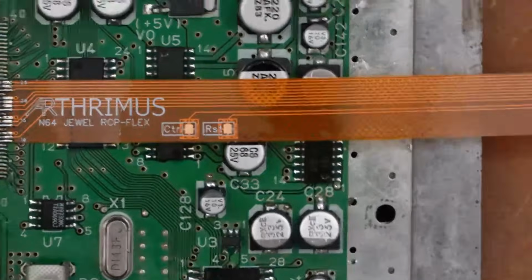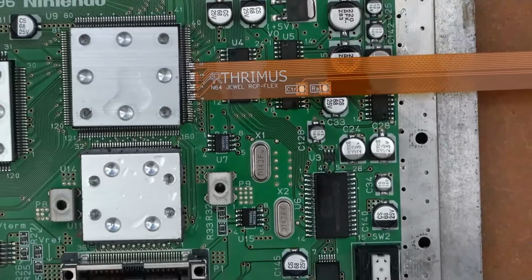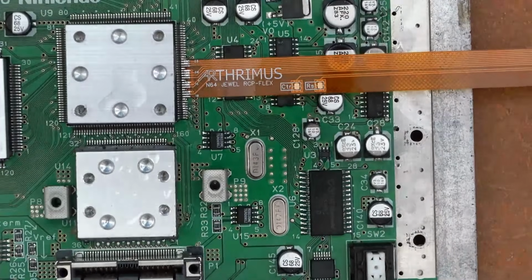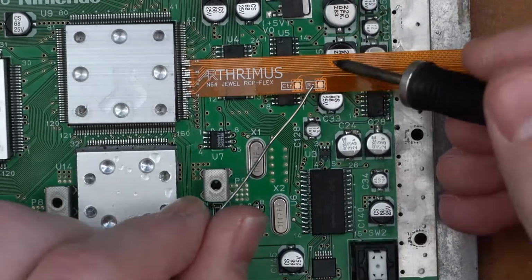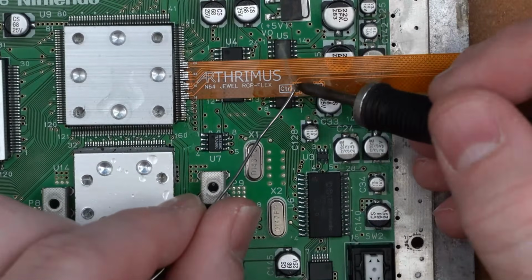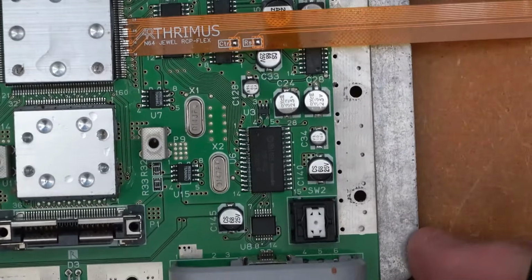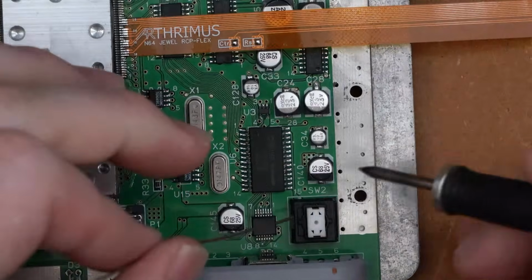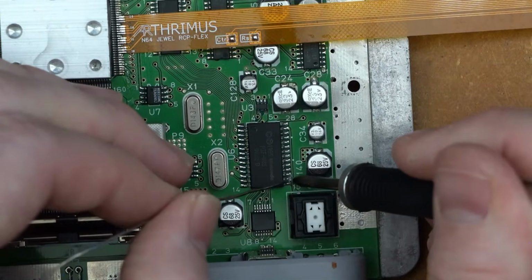All right, so now we need to install our controller and reset cables. We just have these two pads. We're just gonna run a couple of wires down to the locations we need them. So, control, reset. Okay, so control is gonna be on pin 16 of the PIF.